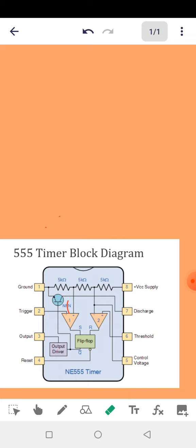But if this were a microcontroller, your reset pin would be very, very important, where you have to, in your hardware configuration, make provision to reset your IC if there is probably a problem with the programming. Maybe it gets lost in the program, you can just bring it back to itself by pressing the reset button. So you can always include that in your design.